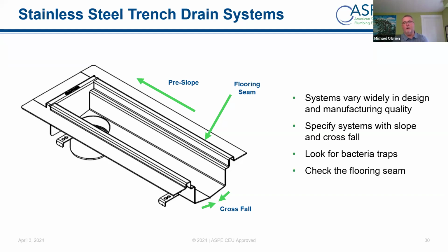So, a high quality fabricated drain is going to take those factors into consideration and make it so that they can be tied in properly. Here where we see this flange, it's like a 2-inch flange all the way around the channel, allows it to be sealed just below the finished tile floor. So any water that gets through a mortar crack or a cracked tile isn't going to seep down between the trench drain and the floor opening.